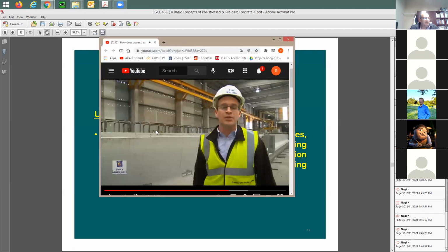Are you talking about the shear links on the top? Yeah, that. On the top, you're not going to have just one beam. You're going to have more than one beam, right? Then the bridge deck is going to be spanning on the top of it. So all of this ties, you're going to put reinforcing right and left, running across and also in the longitudinal direction of the beam itself. And then you're going to pour the concrete deck on the top. So to provide this connection between the beam and the deck, you need to have all of these shear dowels, if you like.